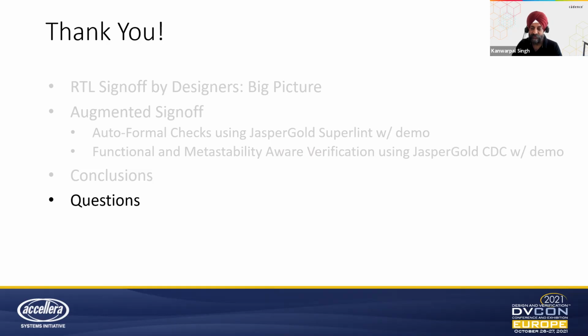So I see one question in the chat. How does JasperLint cope with DesignWare? DesignWare, being a library of components which I think goes with the synthesis tools, you can configure JasperGold lint to say that this is a pre-verified library, and I do not want to do any checks inside the DesignWare, but consider it as part of the design and do the rest of the checks.